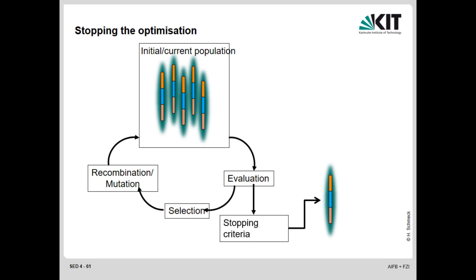There may be more information, so maybe that we have a predicted load profile for our house, maybe we have already scheduled some devices which are still running, and so we have to take them also into consideration. So all this has to be added up in that aggregated load profile, and then we get the evaluation, how beneficial that is, and we take the best string which is generated.